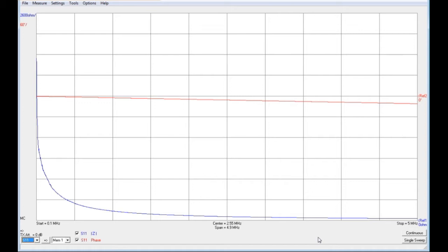And obviously if you do put more than that, then it could risk damage to the front end amplifiers of the equipment. Now that's not very compatible with Tesla coil generators. 1 milliwatt is exceedingly small in that relation. I mean, it's very, very common to run a Tesla coil at 200 watts and above, and the two are not compatible. And it's surprising how easy it is, I've almost done it a couple of times myself, to have your vector network analyzer connected to the Tesla coil and the generator connected to the Tesla coil, and obviously to turn on the generator while it's still connected. Then one has to find another use for the box because the VNA is not going to work after that. So that's something that needs to be taken care of.